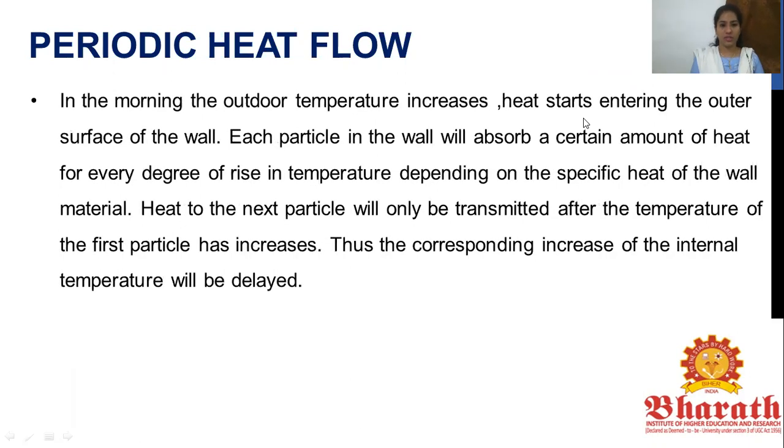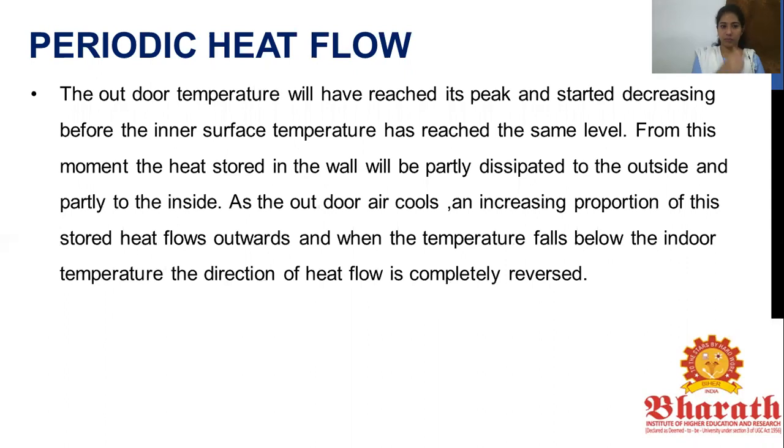So in the morning, the outdoor temperature increases and the heat starts entering the outer surface of the wall. Each particle in the wall will absorb a certain amount of heat for every degree of rising temperature, depending upon the specific heat of the wall material. The heat is transmitted to the next particle only after the temperature of the first particle has increased. So as it keeps on increasing, the heat keeps transferring from one particle to the next, and thus the corresponding increase of the overall internal temperature will be delayed, because each particle has to be heated up in turn.